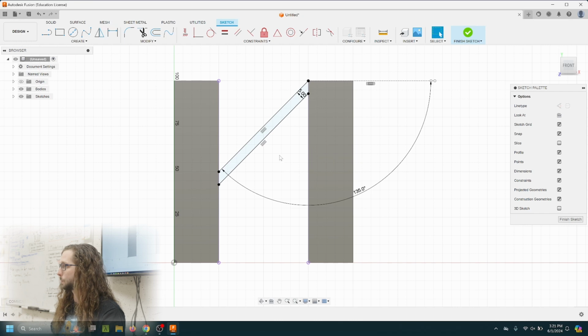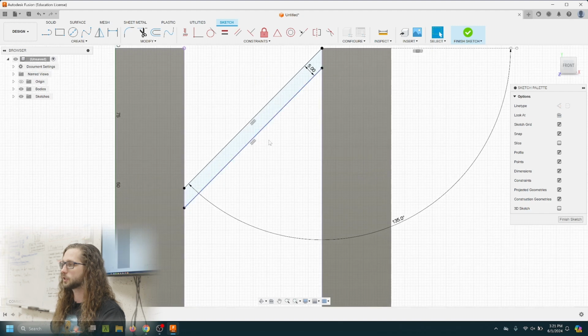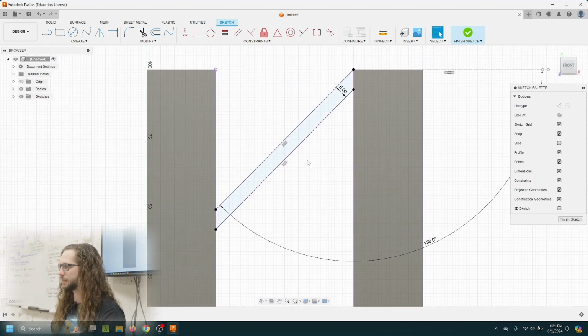If you wanted to move it, can you unconstrain it so that you say, oh, I made a mistake? Yeah, so you'll see when you're in a drawing, Fusion will show you all of the constraints that are happening. So for example, these 2 lines have a parallel constraint. So if you actually click on the constraint itself, you can delete just the constraint and that'll go away. And so now these aren't parallel anymore. If I click this point here, you'll see it's coming up with that coincident constraint. So I can click this and delete it, and now this is going to be movable. So yes, you can always remove constraints later just by clicking on the thing that has those constraints, clicking on the little icon of the constraint itself, and just hitting delete.